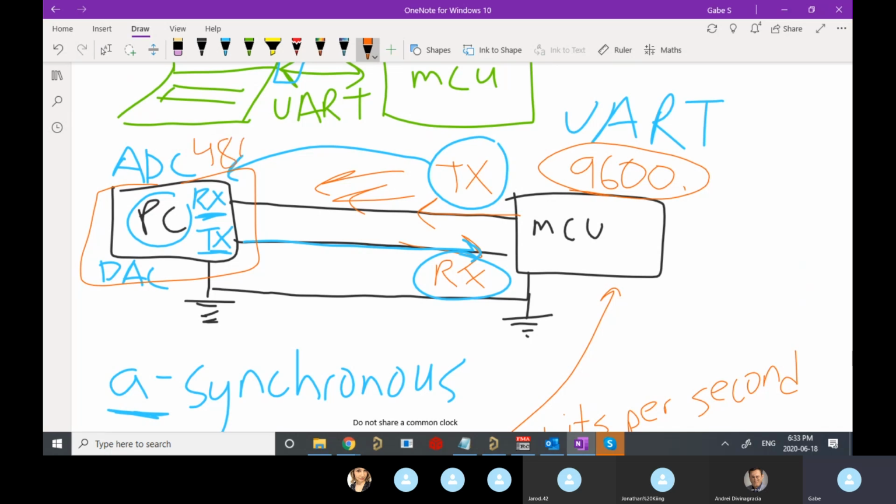Honestly, I'm not sure if this is a real baud rate. 4800. I'm not going to get all the data. And usually you can actually see when they don't line up, because if I'm viewing data on my PC in a little terminal window, like I showed you opening up, usually you'll see a bunch of garbage, right? It actually looks like random wingdings characters and slashes and number signs, like someone's swearing at you, instead of the actual data you expect. So it's usually a good hint that my baud rates probably don't line up if I'm just getting a bunch of garbage.